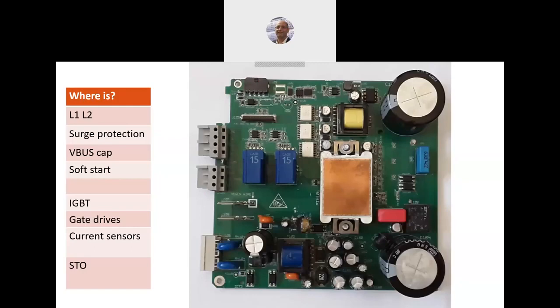Here we operate the IGBT, and if we don't give it 24 volts, the IGBT is dead. If you look here, the main or most expensive devices are the IGBT, and the Hall sensors are also very sensitive; let's say in Pareto, the price is a little bit higher.